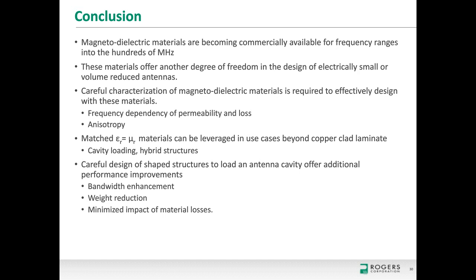What I can say anecdotally is we're working on this system to try to characterize permeability under biasing fields. And as part of that, we've learned just how hard it is to, in a physical structure, drive the material into a saturation region. So practically speaking, you need to be in the hundreds of watts to kilowatts range to really drive the material to saturation for most antenna designs.